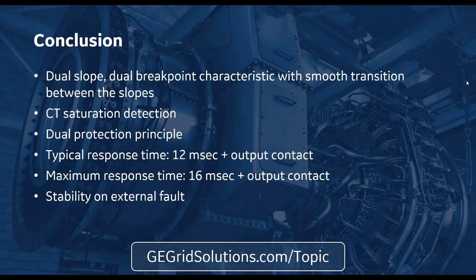If I don't need to worry about arc flash, I don't need to implement a bus differential. But if I'm talking about arc flash, then it all depends. It doesn't matter really the voltage level. It matters how important that bus is to your process. What are you looking for? Are you looking to mitigate arc flash because of the dangerous levels of arc flash?